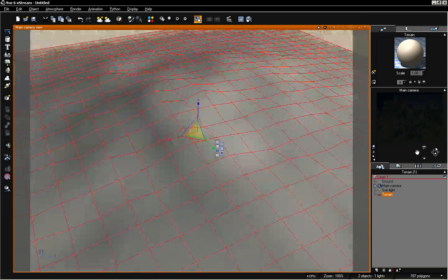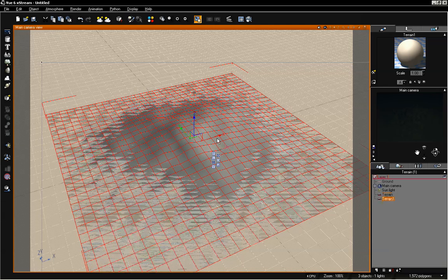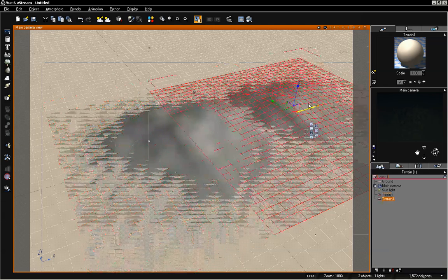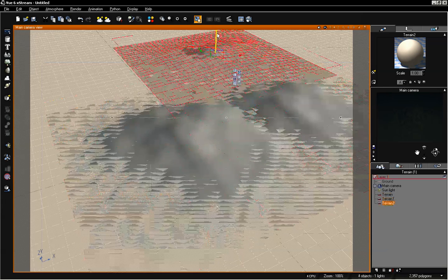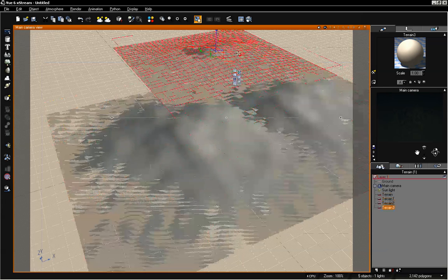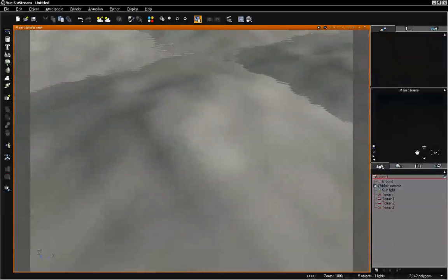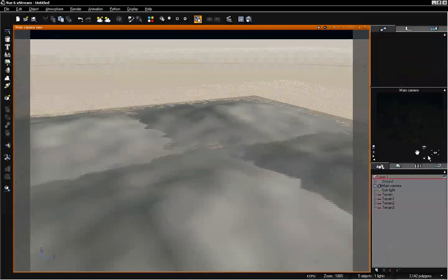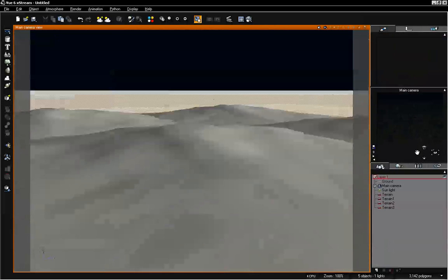our scene. And what I want to do is just copy this, and I want to make sure I change this to our move gizmo. I'm going to hit Control-C and then Control-V to copy and paste this terrain. And then I'm going to do that once again, and we're just moving it across to create 4 different terrains. And that way, once we're in our scene, we're going to have a little bit more variation, and we can start to see into the distance with a little bit of definition.